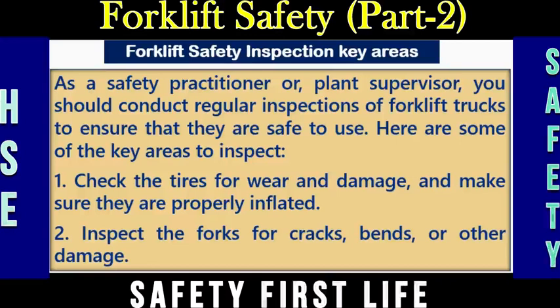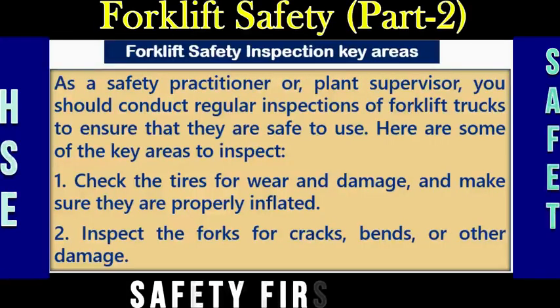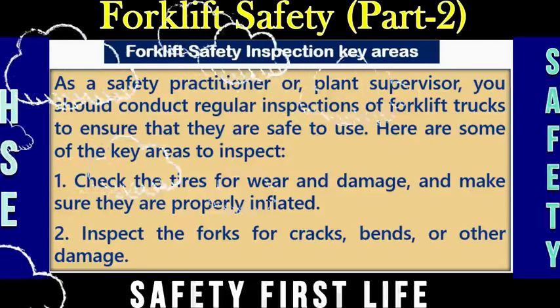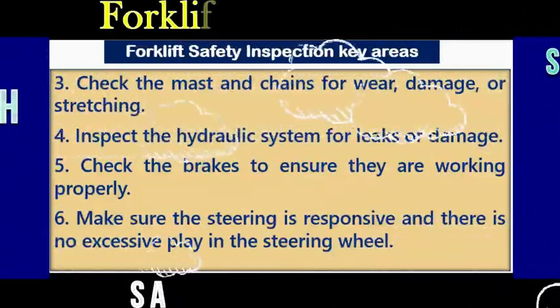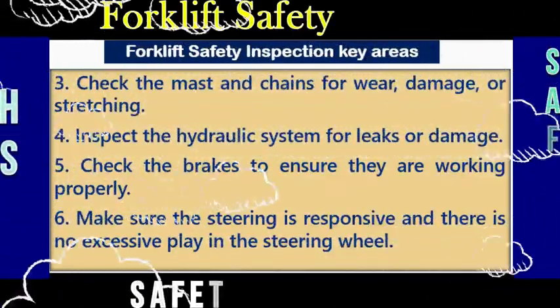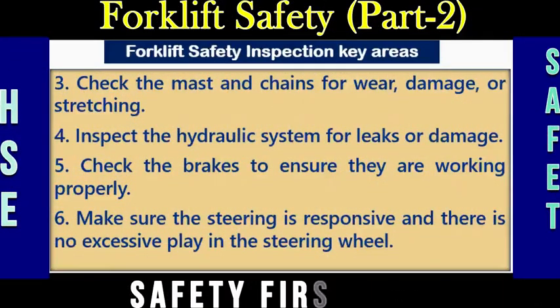Point number 1, check the tires for wear and damage and make sure they are properly inflated. Point number 2, inspect the forks for cracks, bends, or other damage. Point number 3, check the mast and chains for wear, damage, or stretching. Point number 4, inspect the hydraulic system for leaks or damage.